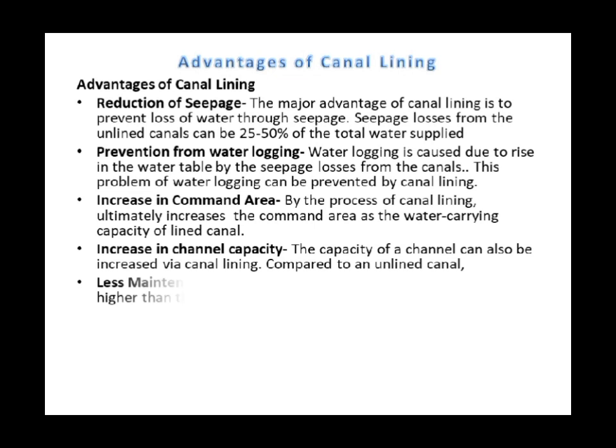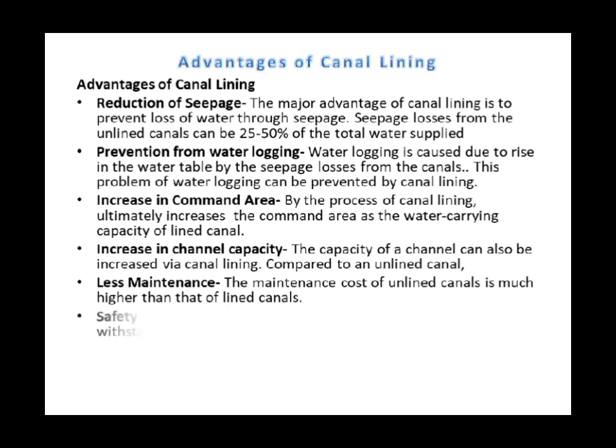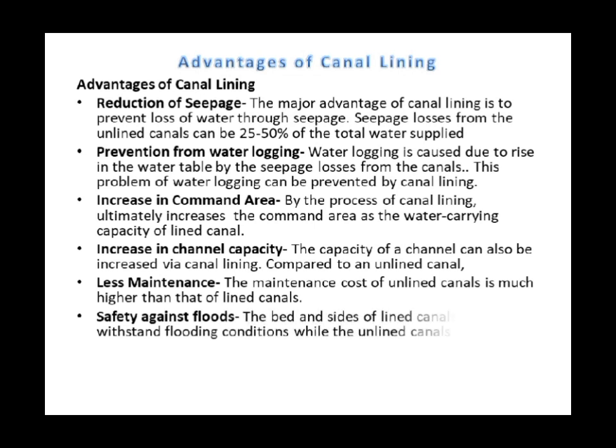The maintenance cost of unlined canals is much higher than that of lined canals. Safety against floods. The bed and sides of lined canals can withstand flooding conditions while unlined canals cannot.